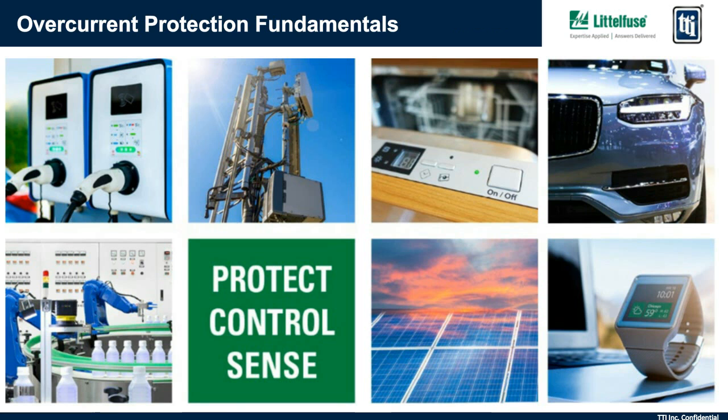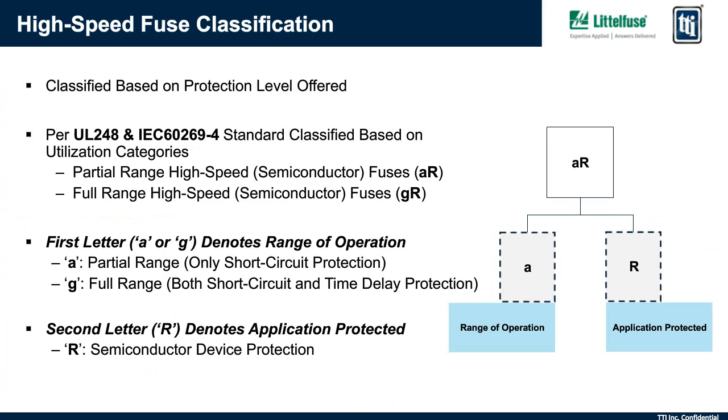So next we'll talk about overcurrent protection fundamentals, which have to do with some key technical details about high-speed fuses and how we break that down in terms of a definition standpoint. So if you're looking at a high-speed fuse and its classification, how is that different than any other fuse? The high-speed fuses are classified based on the protection level offered.